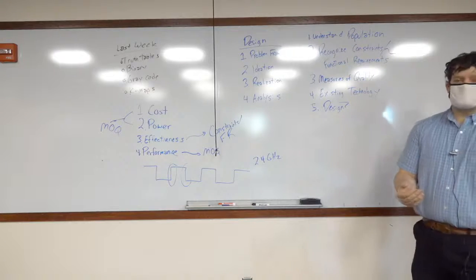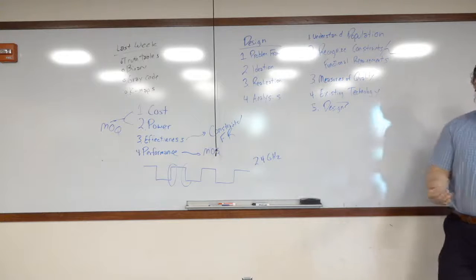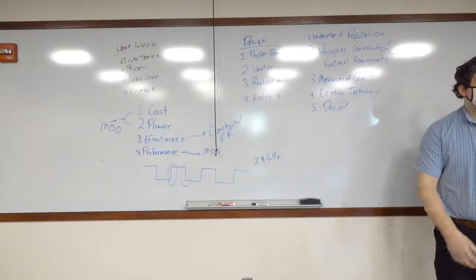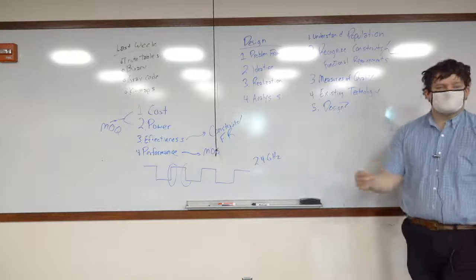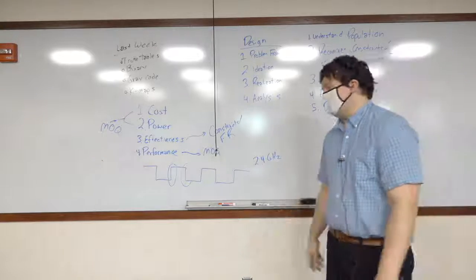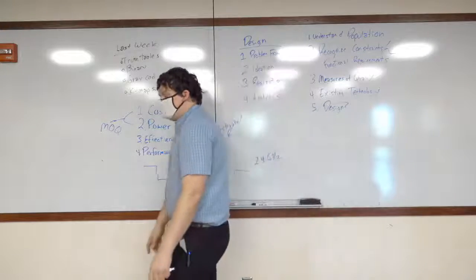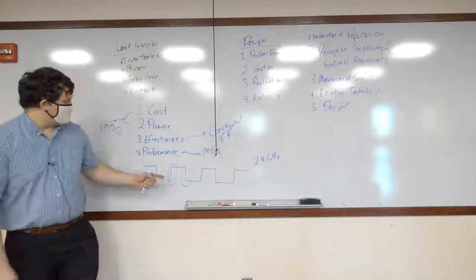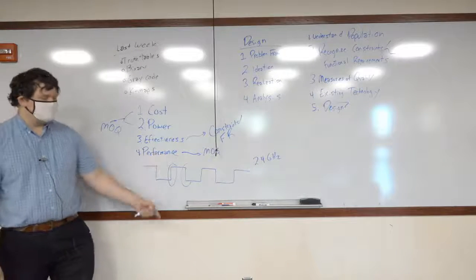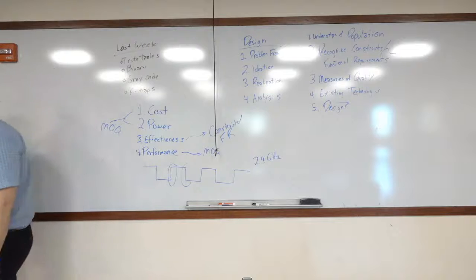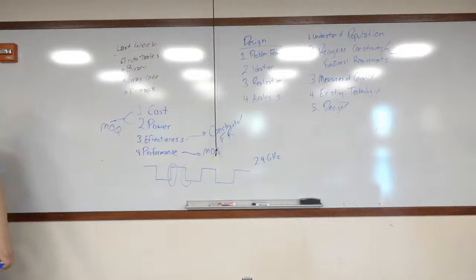If you're doing still frames once a day, your clocking speed can be pretty slow. You're taking a measurement once a day. So all you want to know is once a day. You can have a clocking speed that goes into the minutes per cycle. It may take a minute to go between this peak and this peak. It's going to reduce your power substantially.